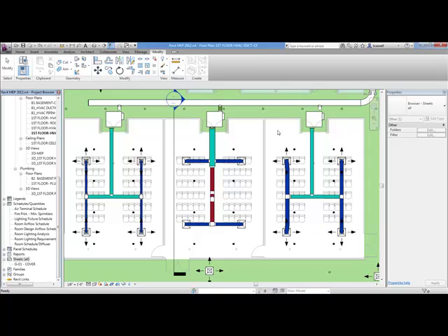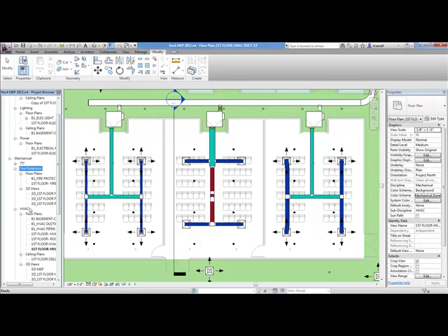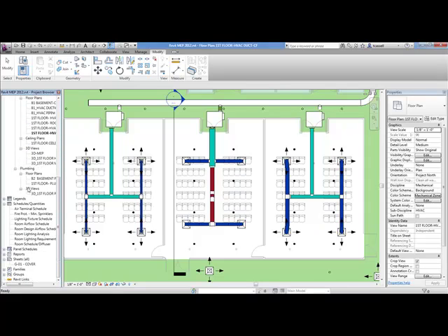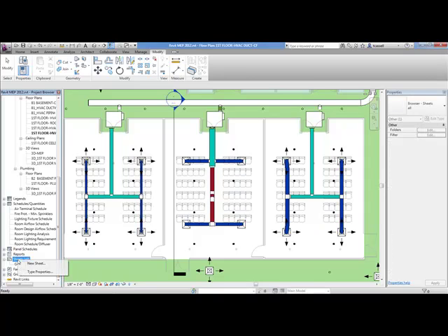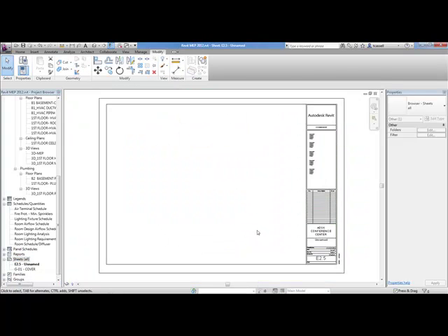The last piece of information that I'd like to show with Revit involves printing in construction documents. Now, Revit is completely capable of carrying a project from the beginning to the end, not just for the floor plans, for the fire protection and HVAC and other disciplines, but also your sections and elevations. It can handle detailing as well, so it does 2D work. But it also handles printing, and it has an area down here where I can go and create sheets.